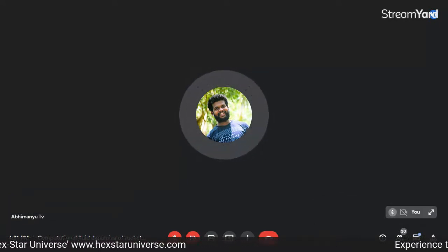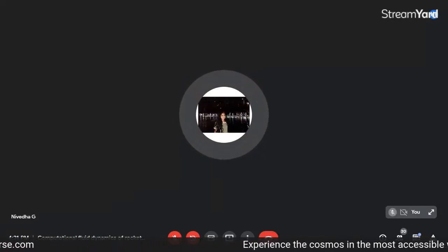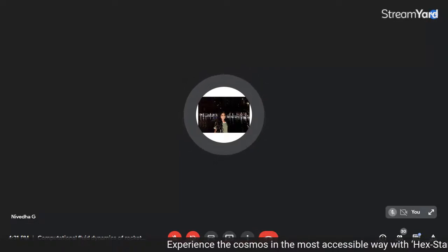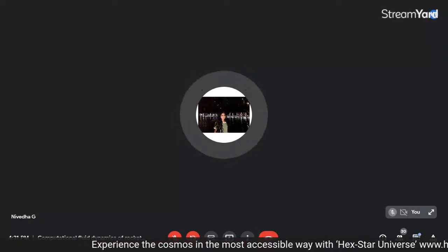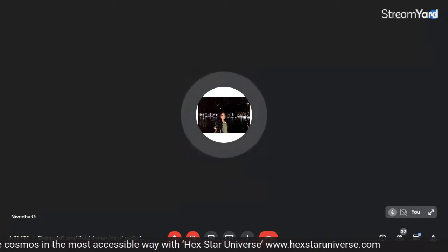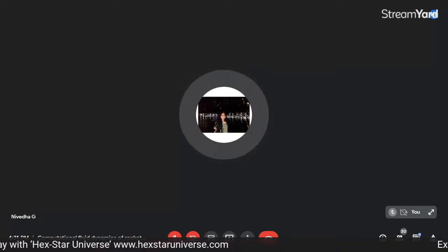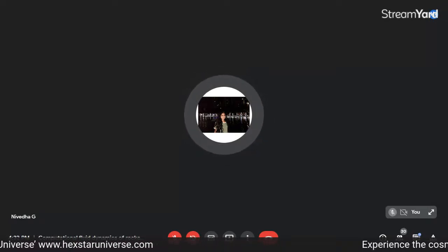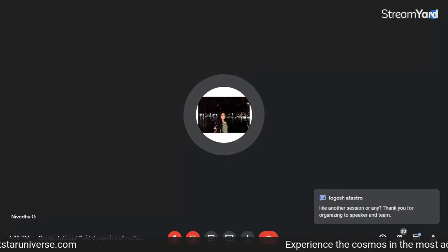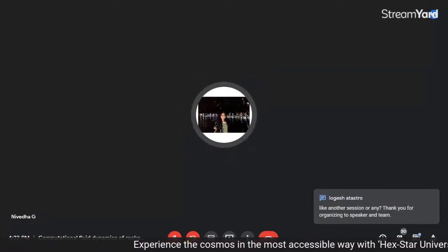Yes, you can see how temperature varies along your nozzle. There is a provision to check your Mach number, your velocity, your pressure, your density, your temperature. Anything you ask, even the force across the nozzle can be measured using the same ANSYS software which I'm talking about.